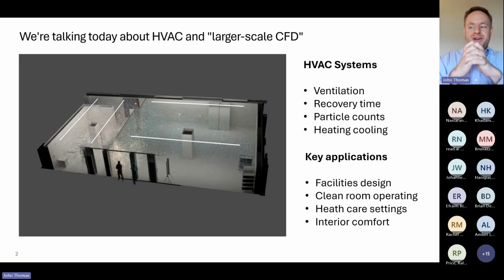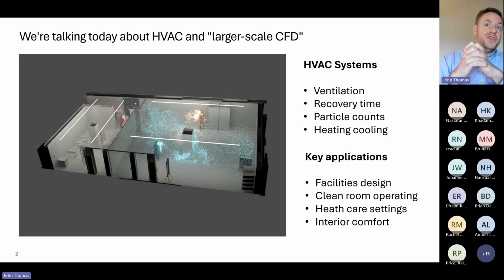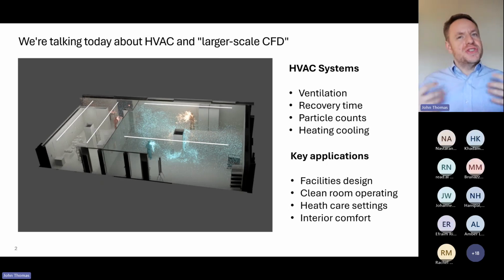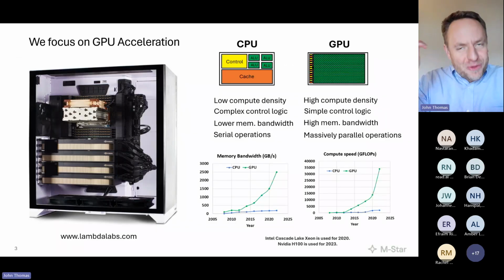One unique thing here is that these facilities can be large, right? Their characteristic length scale may be on the order of several tens to hundreds of meters, and that's very different from a lot of the smaller systems we're used to studying. So I do want to touch on how turbulence scales and how you consider systems that are big, where the voxel size might be, I don't know, 10 centimeters compared to the sub-millimeter we frequently see in more process applications.